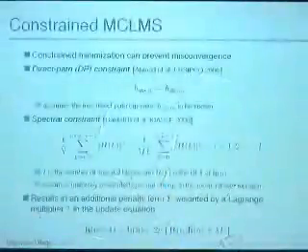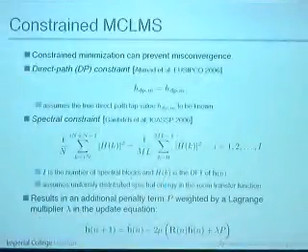Another observation that we had is that this misconverged solution has some strange low-pass effect. It always tends to this low-pass tilted spectrum. What we thought of doing is to impose a constraint that your spectrum should have somewhat uniform energy distribution across all frequencies.